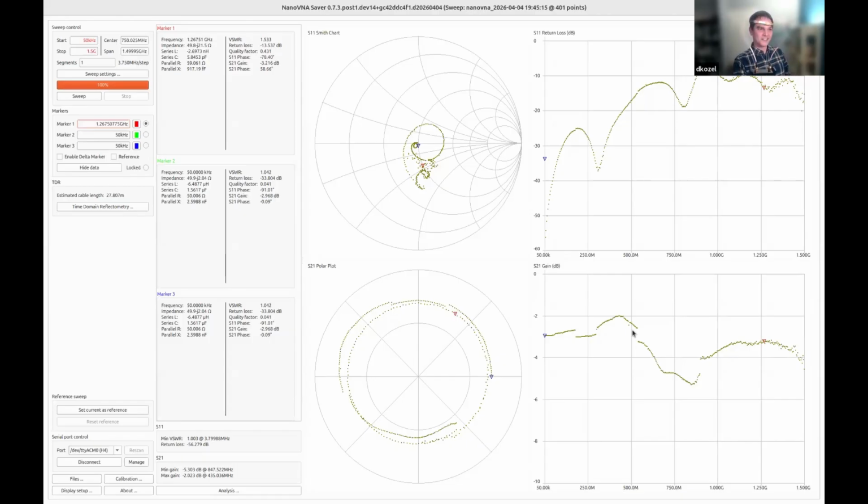One thing we'll note is I have a big coax bend here because these weren't very long leads that I put on. By bending that, I have shifted how the coax is behaving. That calibration is now no longer totally valid. But we can see it's decent up to 500 megahertz. And our return loss is very, very good. Almost all the power going forwards is not coming back.